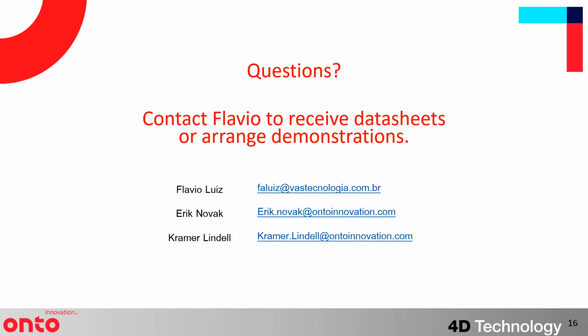We do actually calculate both the R parameters, so Ra, Rq, Rt, as well as many of the S parameters, which are the three-dimensional surface parameters. However, as the system noise floor is 2.5 micrometers, there are only certain surfaces on which that will be valid. If you have a polished metal surface or a fairly smooth metal surface, chances are the roughness is beneath our 2.5 micron noise floor.